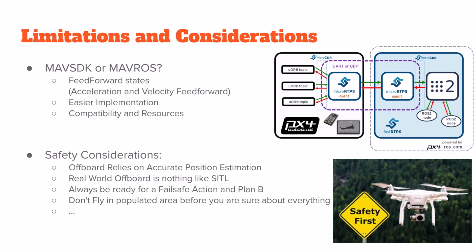Before implementing our project, let's review some limitations and considerations. As I told you, there are quite a few MAVLink APIs out there. MAVSDK and MAVROS are the well-known ones for the best compatibility with PX4. Each of them has its pros and cons.